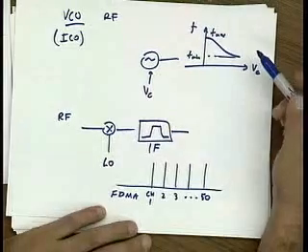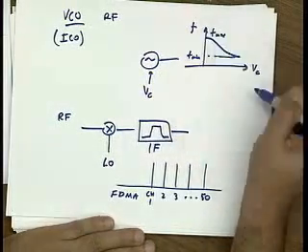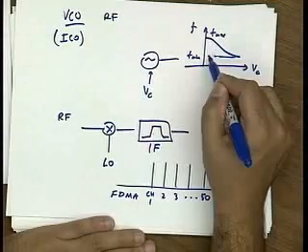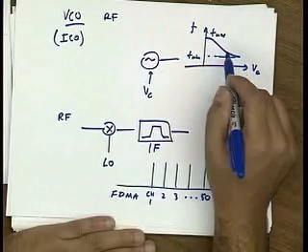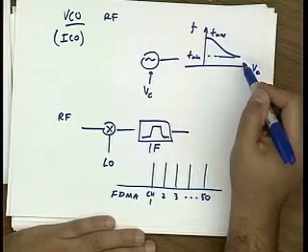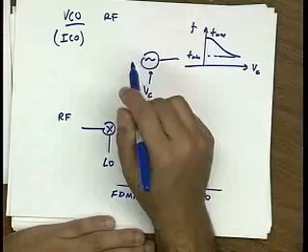In an ideal world, this curve would be really linear and very predictable, and I could just store in some ROM the right value of control voltage to hit every output frequency. But unfortunately, we don't live in an ideal world. We live in the real world, where this curve is a kind of nasty shape, and it varies all over the map over process and temperature.